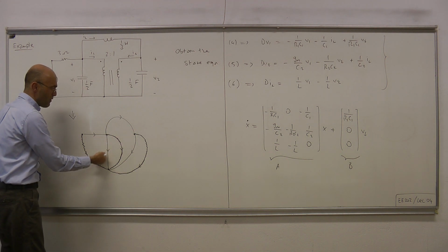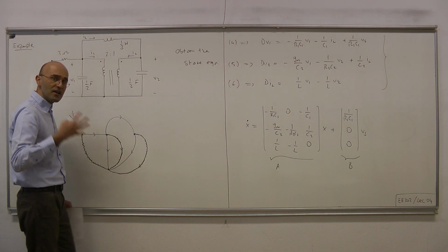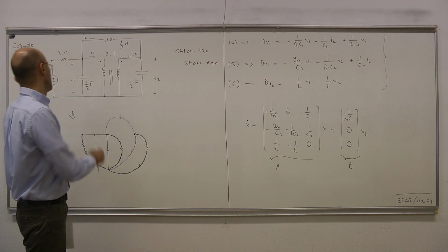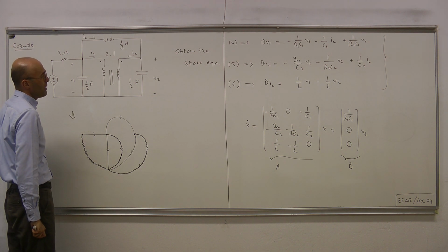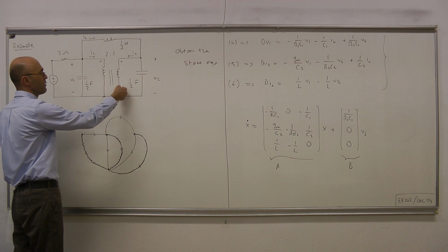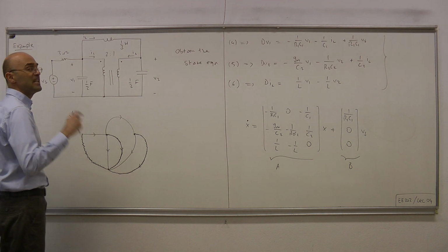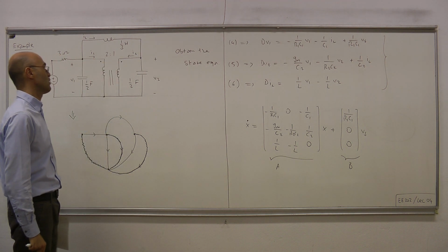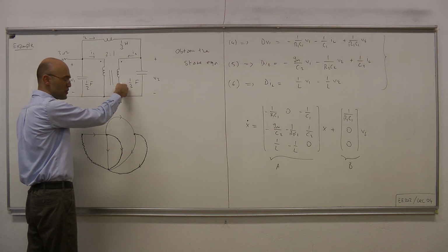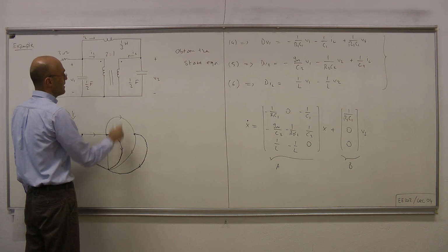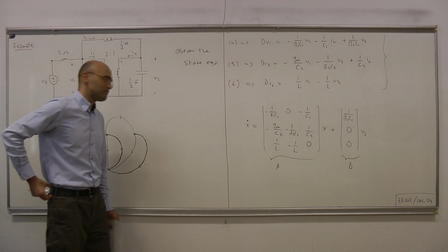But if you include that capacitor in your proper tree, then here you obtain a loop. In that case, that tree is no longer a tree, therefore we cannot include this capacitor in our tree. And then perhaps you can say, what if we have chosen the other transformer branch? Can we increase the number of capacitors in our proper tree? Then it turns out that for this example, at least, if you choose this branch instead of this branch, again you can only choose one of the capacitors in your proper tree. So there's not really